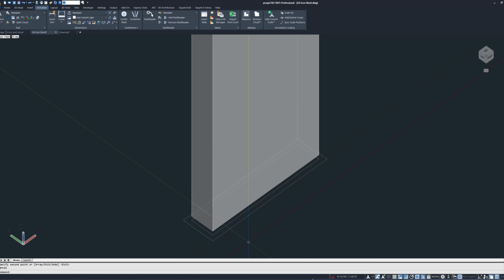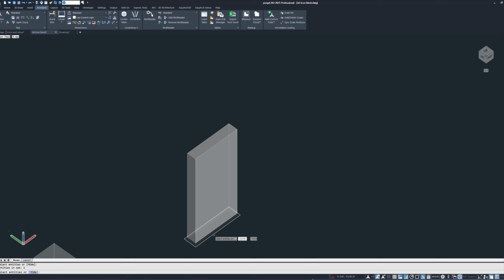Now we know that we can use this temporary polyline as a reference to get a good height. 3D drafting takes some experience to know what to do at the appropriate time. That will only come as your skills grow in coming up with shortcuts that will aid in the actions shown. With two polylines drawn, I will use one to extrude and the other line as a height reference. Pay close attention to which line is extruded and which is used for height.